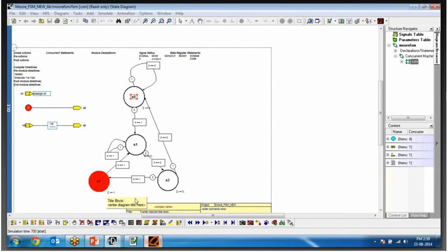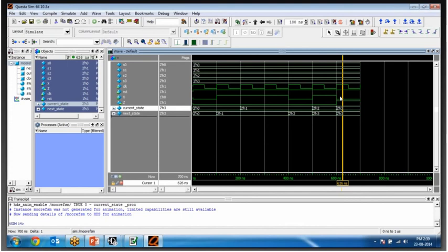So again going back to the FSM interface, this is the output that we have seen. Now we are confident of executing any pattern using a Moore FSM. But we are observing a one clock period delay here, and that will be there in all Moore FSMs.